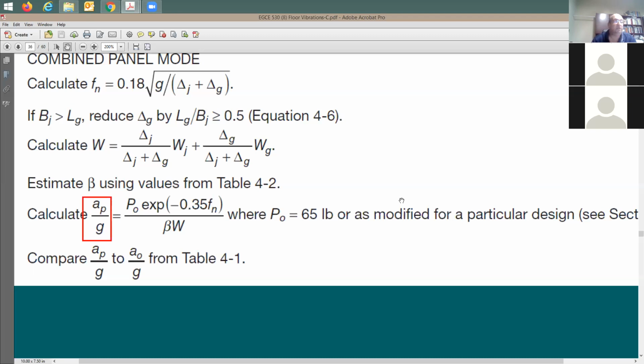50%. You don't know, because the acceleration also has a direction, right? It goes like in waves. So you don't know exactly when the two waves are going to be in the same direction at the same time. This is going to be very tough to determine. So maybe you'd like to do the square root of the summation of the squares, right? So you say the square root of the summation of this acceleration plus the other acceleration. Say most likely this is what I'm expecting, right? Okay. Then you compare it to the 5%.